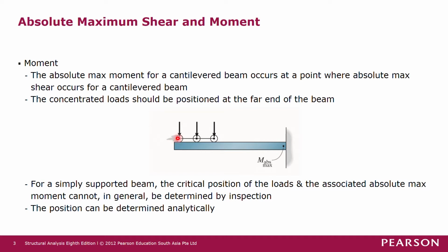For moment in a simply supported beam, the critical position of the loads and the associated absolute maximum moment cannot, in general, be determined by inspection. So in this case, we cannot tell where the absolute maximum moment will occur, and we also don't know how we are going to arrange the loads at which position.